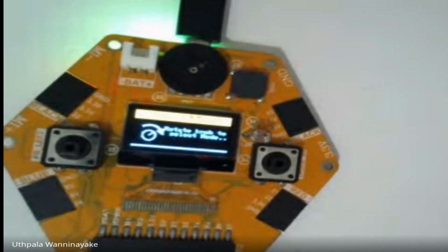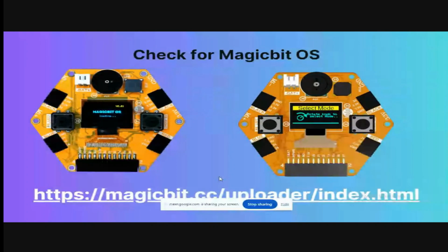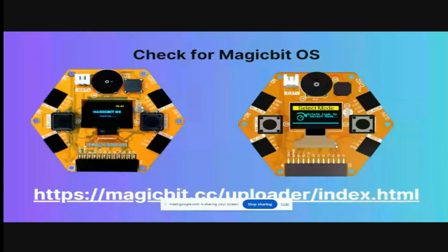You can search for it as Magicbit Web Uploader. Then make the connection between the uploader and the Magicbit first, and then click on the Magicbit OS, the first option, and wait until it uploads. Once the OS is uploaded completely, you will get a pop-up that the OS has successfully uploaded. Then you can click okay and disconnect the Magicbit from the uploader.